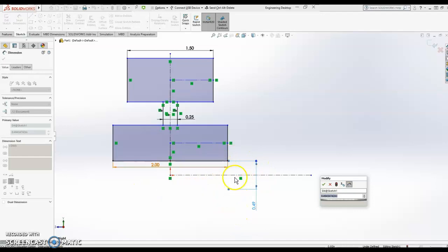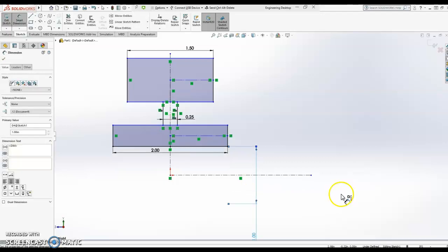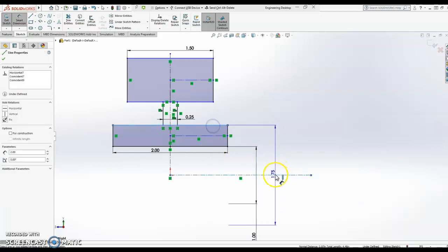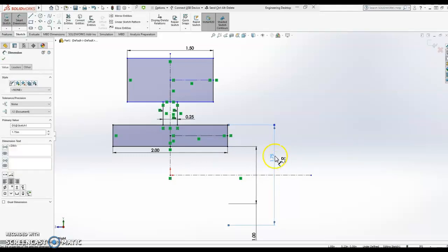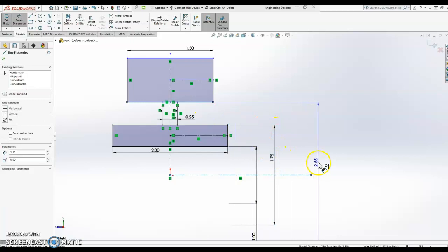So what I've done is I said, hey, this is going to be a circular part, and I'm putting in the diametric dimension, so the dimension on the diameter. And so let's go. That first one should be an inch. That slides up. The second one, that inside rim, is going to have a diameter of 1.75. So I'm going to click here. And since I was already using the Centerline, it's smart enough to go, oh, you're putting in another diametric dimension. So I'm going to put that down, and that one was actually pretty close, 1.75.